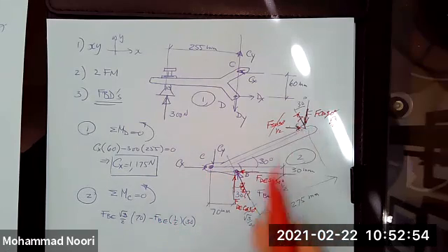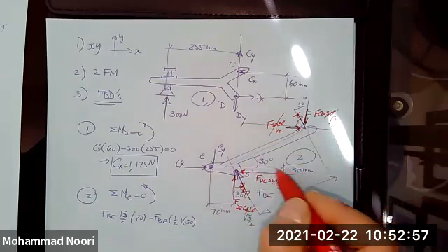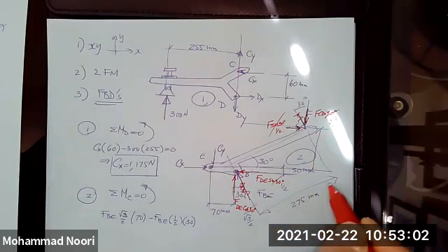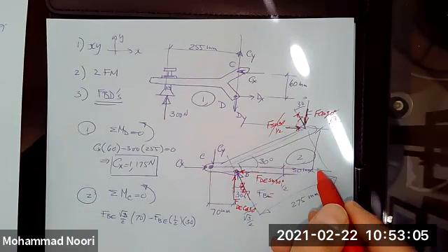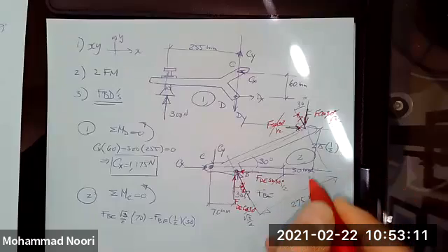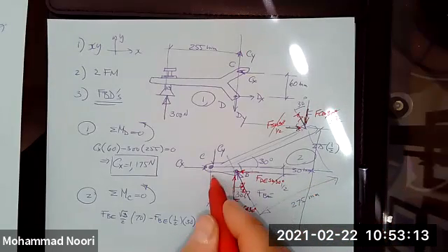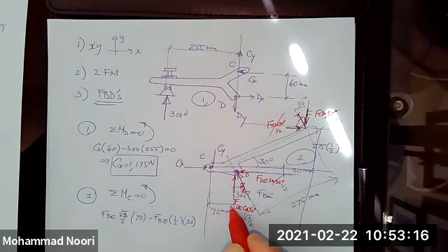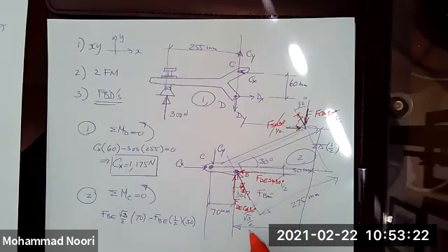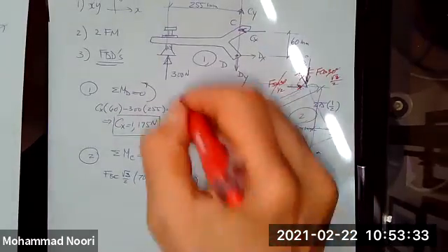Okay. How about this one? This distance I need. This distance is 275 sine of 30. So this is 275 times 1/2. And I also need this distance. Well, this one part I have, I need this one. This would be 275 cosine of 30. So 275 square root 3 over 2. Okay? So the moment of this force about this point would be negative.